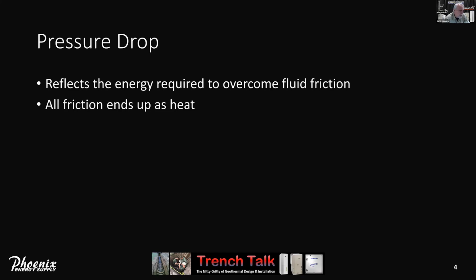So not only is the pump adding energy to the system, if our water temperatures are going up, all the air conditioning efficiencies are being impacted as well. Every degree our loop is warmer than what it could have been is another percent loss in efficiency. And I've seen jobs where pumping energy is what's driving loop temperatures out of sight. So a bad selection and poor control can seriously impact the efficiency of the geothermal system.